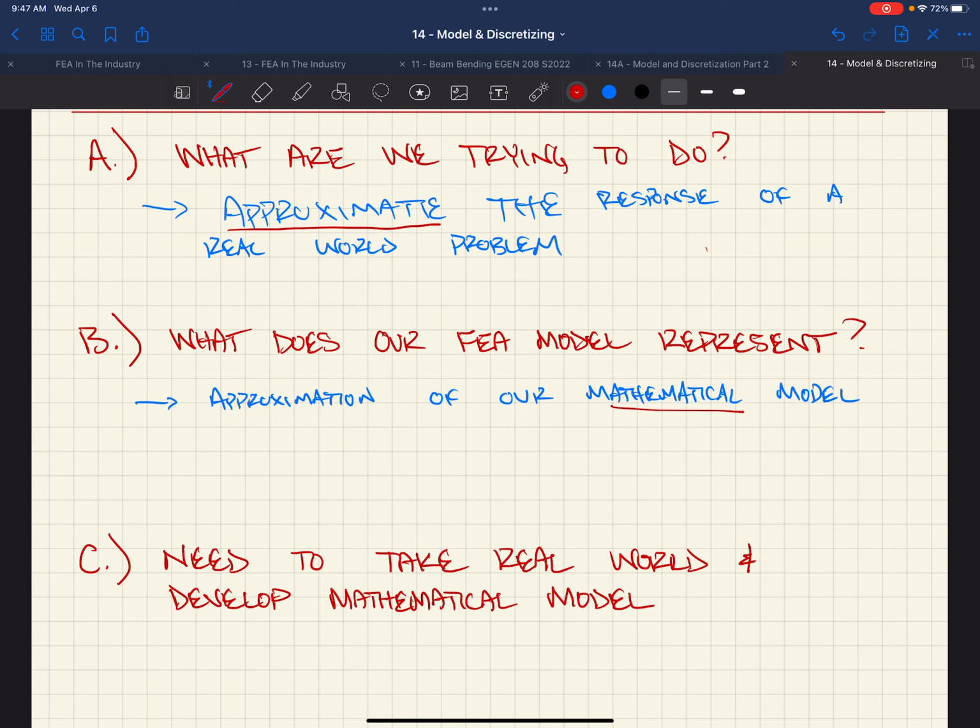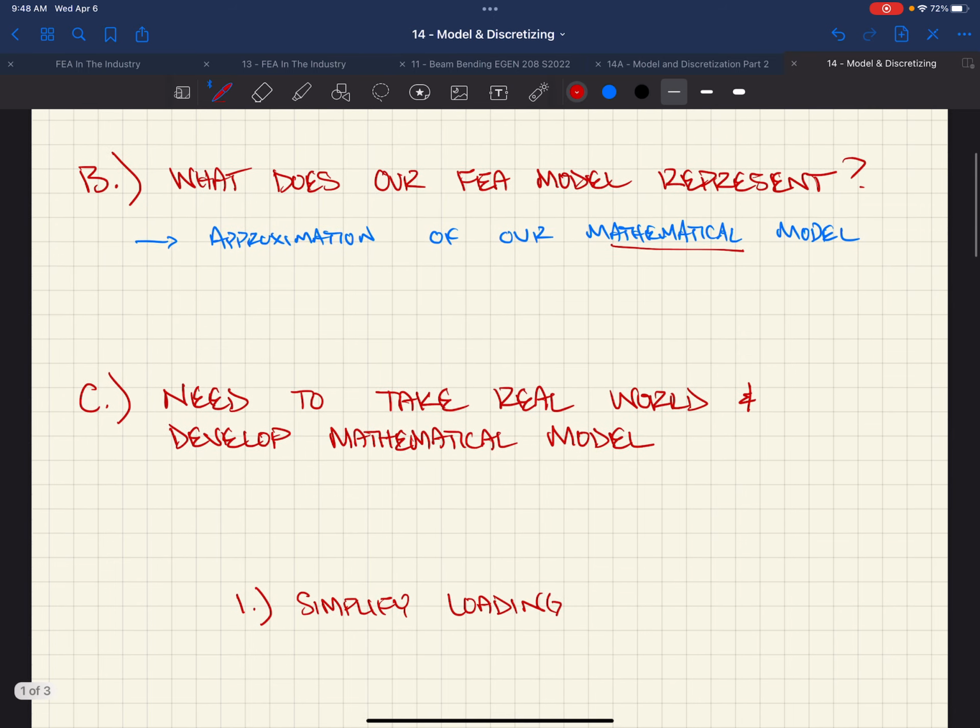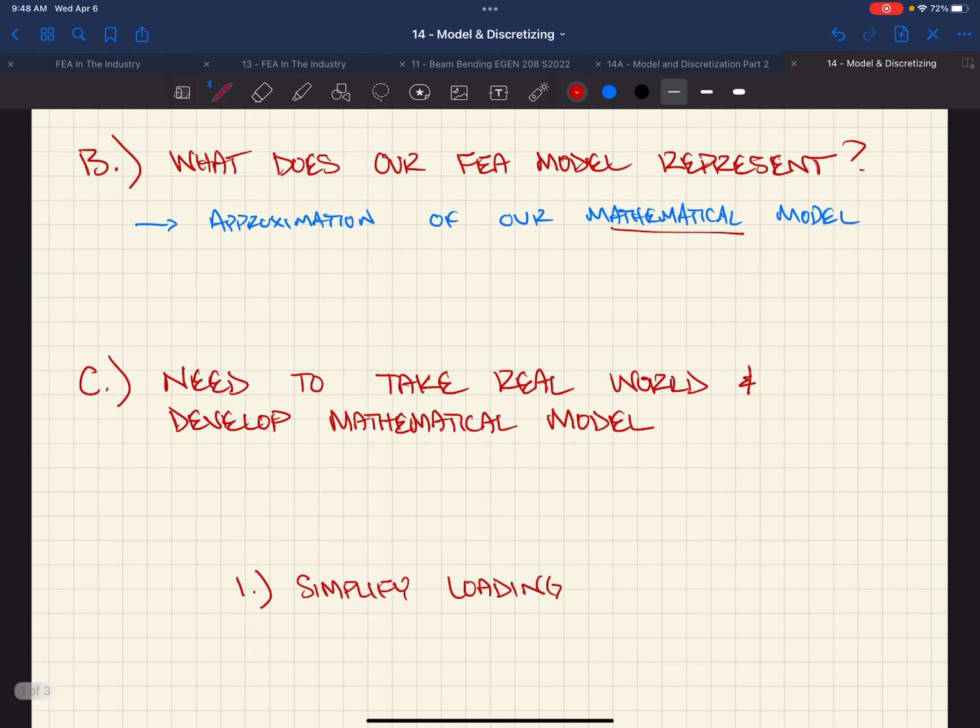Yes, Aaron? For the hand calcs, can we just use the cantilever tables, like the tables in the steel manual? No, you don't have to derive it. You don't have to solve for the equation for the deflection of a cantilever by integrating the moments. Use some mechanics for the forces and moments, and then use the steel manual for deflections. The manual also has the shear and the moment too, if you want. It'd just be two separate cases.